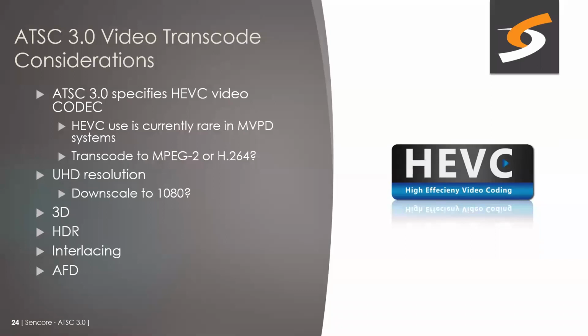High dynamic range is definitely a consideration. We're seeing a lot of effort to use HDR in ATSC 3.0. That HDR will need to be dealt with in terms of being able to reuse it in these systems. Whether or not these MVPD systems support HDR is dependent a lot on the system, but likely some kind of HDR to SDR conversion will need to take place inside the transcoder to make a compatible signal.